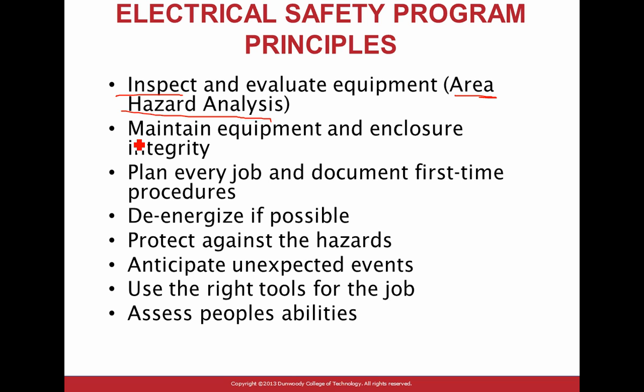You can't just install the system and not maintain it and expect it to be safe. It has to be maintained safely. And then after that, gentlemen, you start working on it safely. That's how you guarantee safety. The equipment that you install has to be safe by being UL listed or any other third-party verification. Does that make sense? Safe equipment by listing, safe design and installation by the NEC code book, and safe maintenance by 70E or your preventative maintenance program that every building has.